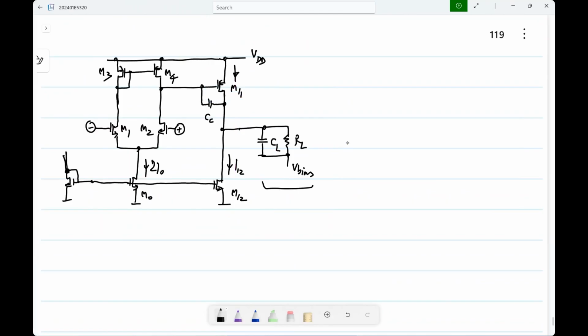This is the load, and that's the load current. Okay. So, like I said, you can use this with both resistive and capacitive loads. It's actually used when the loads are pretty heavy, meaning load impedances are quite small. So now, what are the limits on IL? How much current can you pull out of the op amp? How much current can you push back into the op amp?